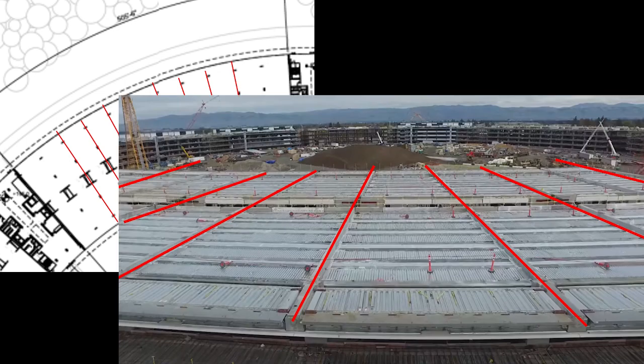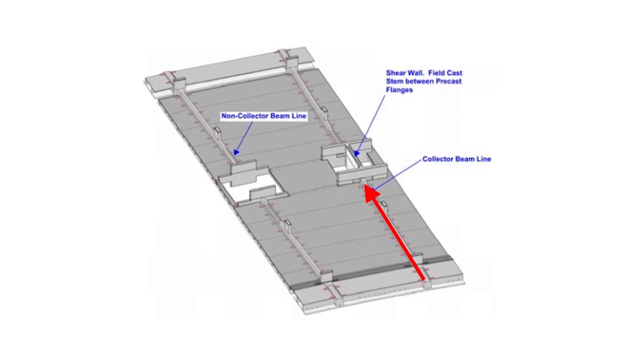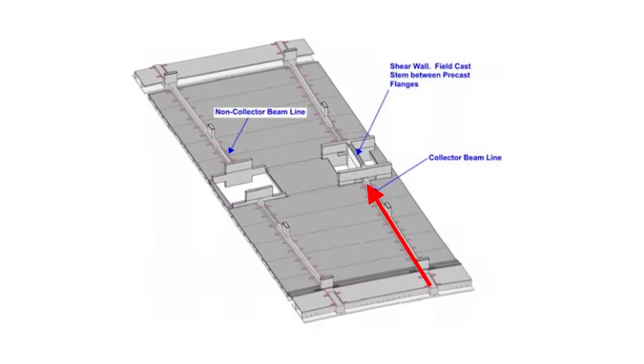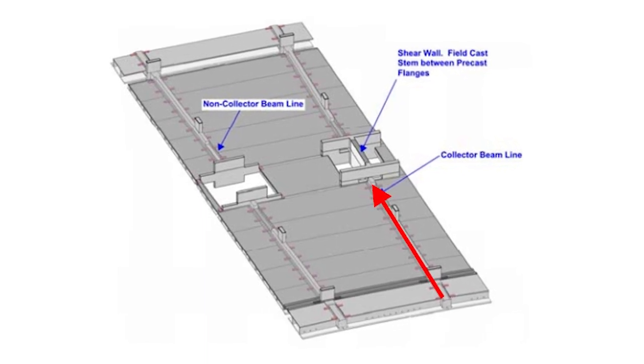These girders repeated themselves at every interior radial grid line. The girders also had to perform as collector elements, delivering more than 400 kilopounds of force to the shear walls. The surface space below the girder was shrouded with either an architectural beam cover or partition framing where walls were placed.